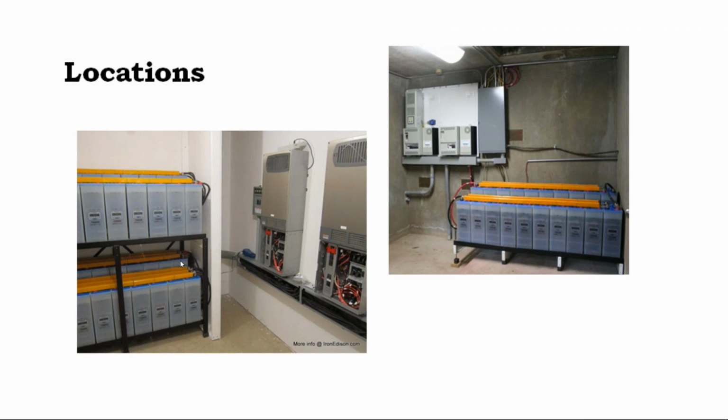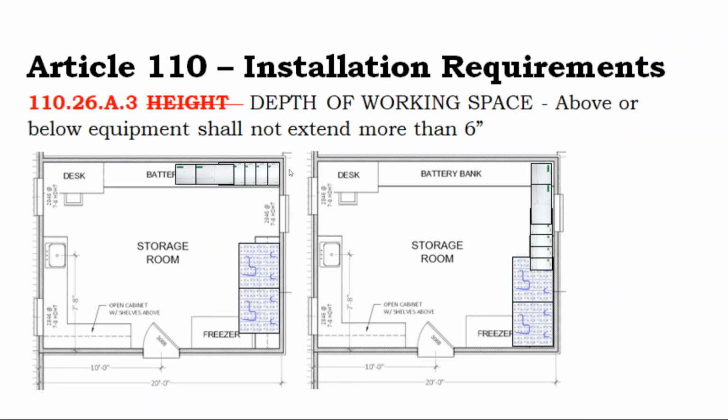And what that implies is you can't just put the battery up against the wall. At minimum, you're going to want to be able to walk around the battery in order to service it. So it's probably better if your battery has a long end and a short end to put the short end against the wall and have the battery stick out rather than the long end against the wall, simply because your inspector might say, look, it's more than 6 inches to get to this back cell here, and so you're going to have to access that cell somehow.